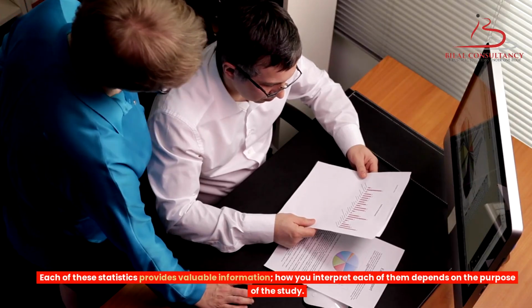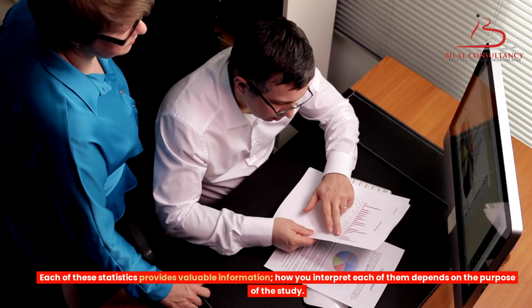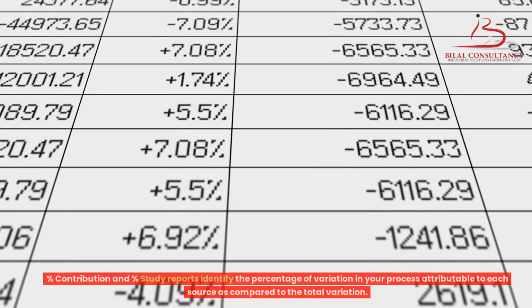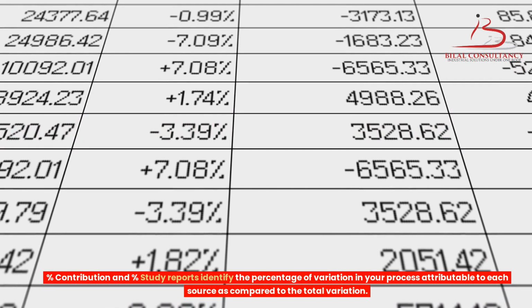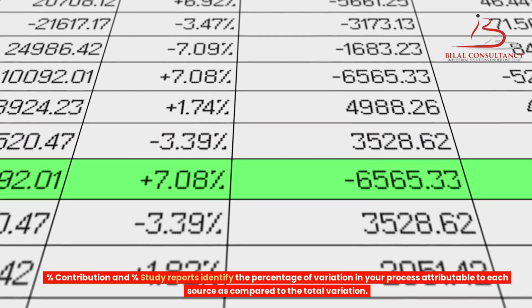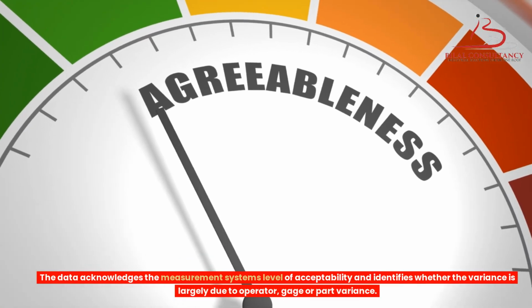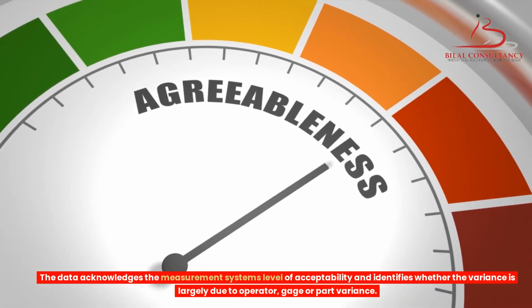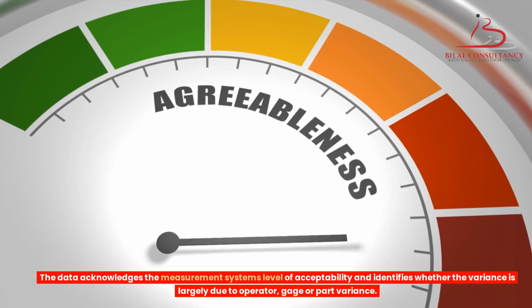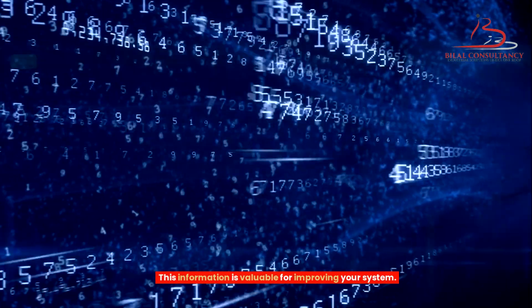Each of these statistics provides valuable information. How you interpret each of them depends on the purpose of the study. Percent contribution and percent study reports identify the percentage of variation in your process attributable to each source as compared to the total variation. The data acknowledges the measurement system's level of acceptability and identifies whether the variance is largely due to operator, gauge or part variance. This information is valuable for improving your system.